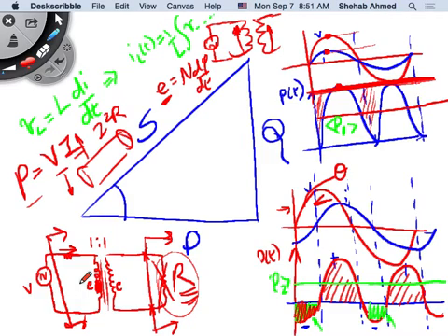You cannot charge a battery with reactive power. It's power that's used to set up magnetic fields and collapse them. Remember, magnetic fields here are time varying, and in a transformer it has to be a time-varying magnetic field. So you set it up, collapse it, bring it in the other direction. Set it up, collapse it, bring it. You follow the hysteresis curve, right? And that's where the exchange of power between the load and the source happens. So this negative portion has an associated positive portion that goes back and forth between the loads and the supply. And that's reactive power going back and forth.